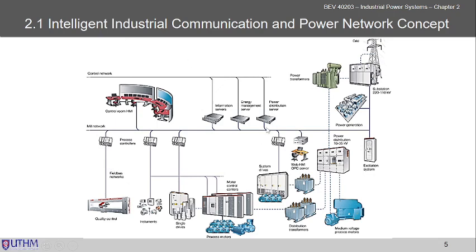Yeah? That's the intelligent approach. Even for controlling our power factor, let's say our power factor suddenly goes down due to the load here, our control room will detect the poor power factor, and it will instruct automatically to increase the power factor back, for example. Same for the voltage.